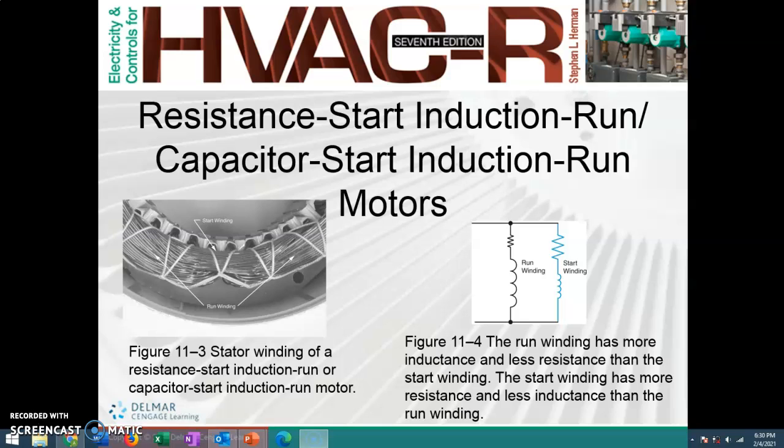Okay, so both motors operate on this same principle here, the start winding will only be part of the operation until the motor hits about 75% of speed. We'll get to how that happens in just a minute, but remember that number, 75% is very important.